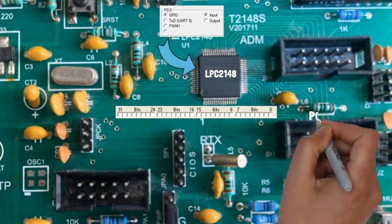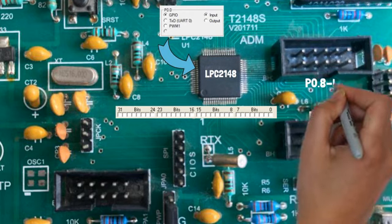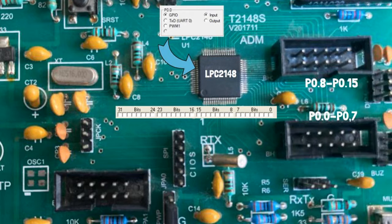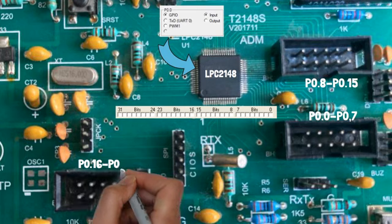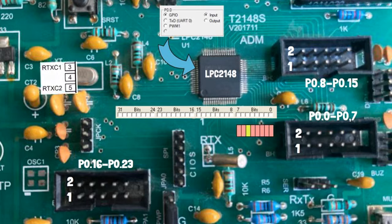In this demo board, I/O pins are terminated in groups of 8 on a header. If our LED is connected to header 1, we use bit 0 to bit 7 of the 32-bit register. If we connect the LED to header 2, then we use bit 8 to bit 15. If we connect the LED to header 3, then we use bit 16 to bit 23.